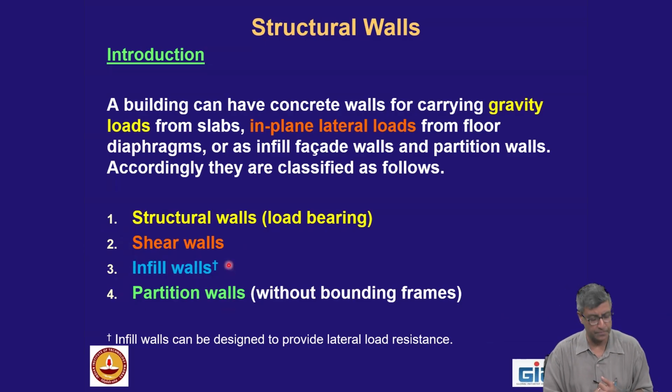What are infill walls? Infill walls are just filling up, covering the space. They are not even carrying any load except their own weight. Typically, we do not design infill walls. However, infill walls can be designed for lateral load resistance. And if you are using infill walls made of what are called concrete masonry units, you can even reinforce them. This type of technology is there, so that you take advantage of the infill wall and bring down the cost of casting a concrete shear wall.